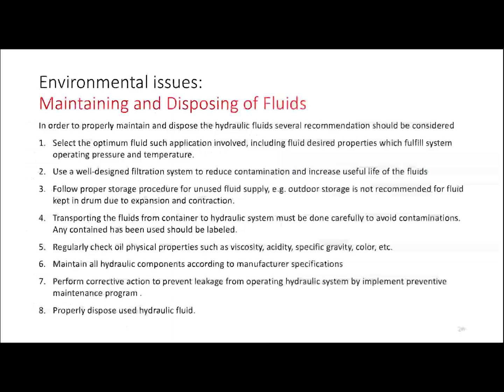And then follow proper storage procedures for unused fluid supply. Then transporting the fluids from the container to the hydraulic system must be done carefully to avoid contamination. And then regularly check oil physical properties such as viscosity, acidity, specific gravity, and color.